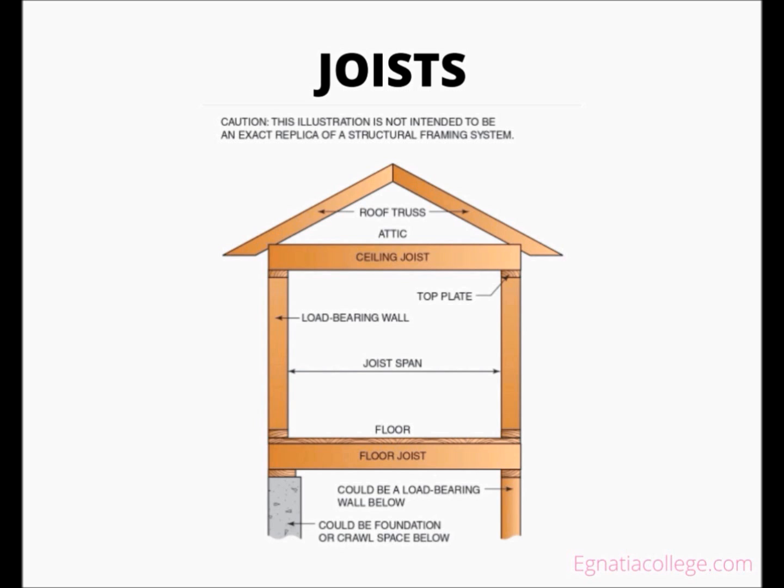Because a joist has a different structural purpose from a wall stud, it also has different drilling and notching code regulations. Some codes do not allow any holes to be drilled in the middle 1/3 of a span. Other codes require a joist to be reinforced with exterior grade plywood if a large diameter hole is to be drilled through it. Some codes do not allow a hole to be drilled in a floor joist in the area that has a load-bearing wall directly above it.